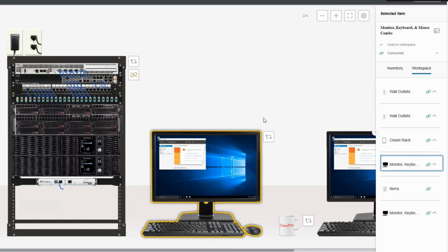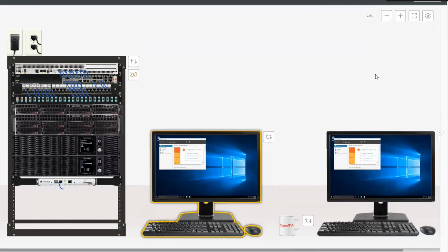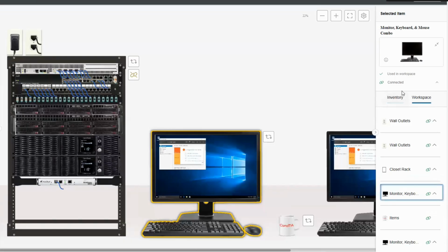The other tricky part is sometimes if you accidentally click here, on the small arrow right here, it just moves like that and then you're not able to see it. You wonder, where can I find the inventory and workspace, or how can I see that? The only thing you need to do is click right here, and then it will pop up.